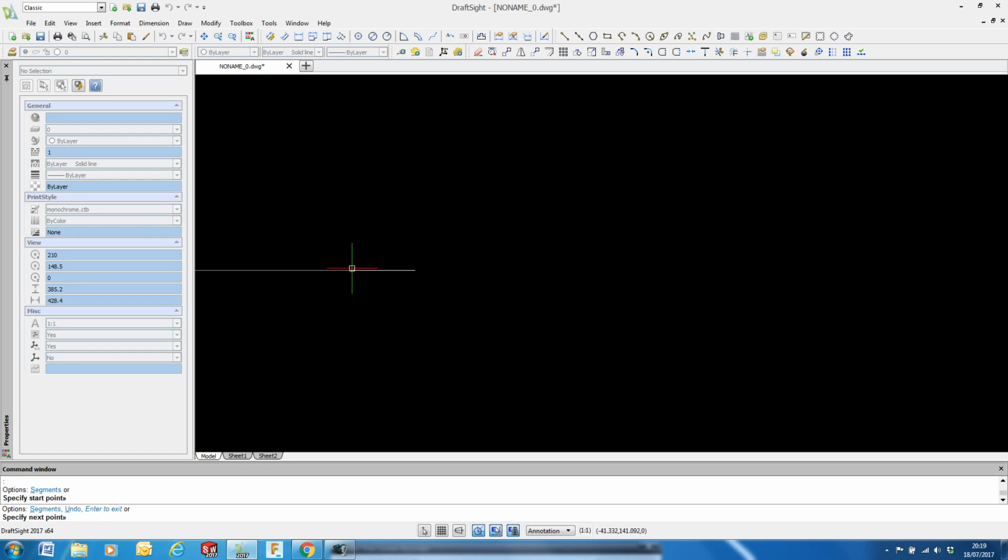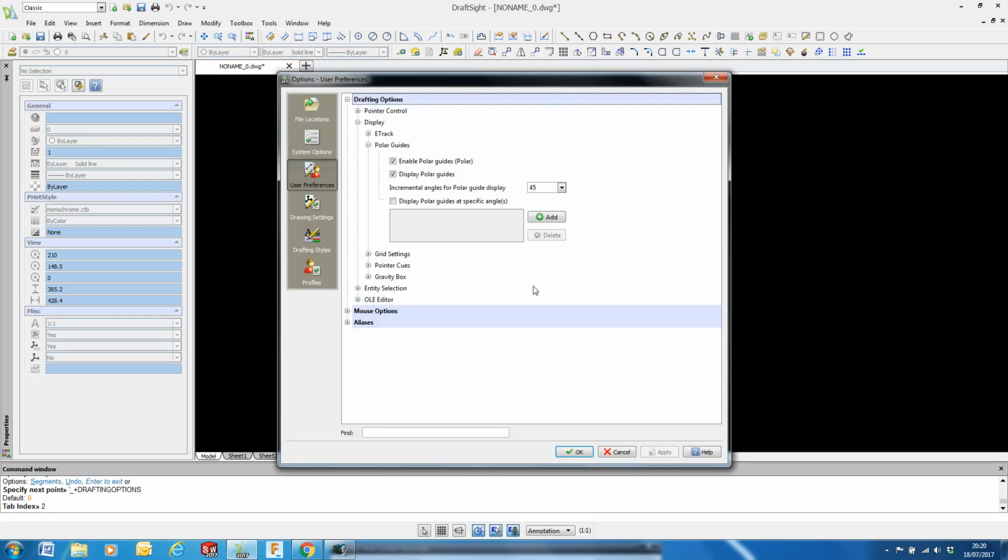I have a polar lock in several locations. There's a polar lock at some angle, and I've got the orthogonal turned on. So this polar radial lock is quite useful. At the moment I know my settings are every 45 degrees. If I come down to this button, middle button at the bottom, polar, if I right click, the same as all of these buttons at the bottom, go into my settings, takes me to the appropriate page in the user preferences, and I can see 45 degree